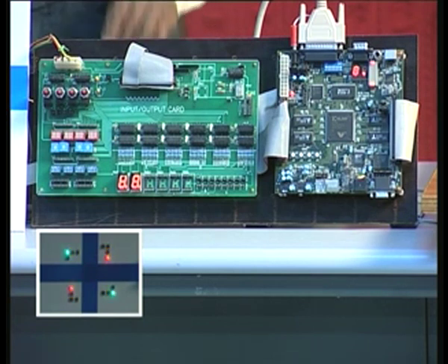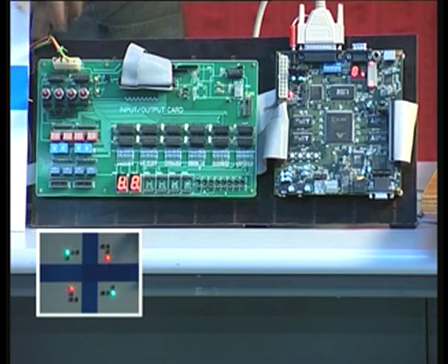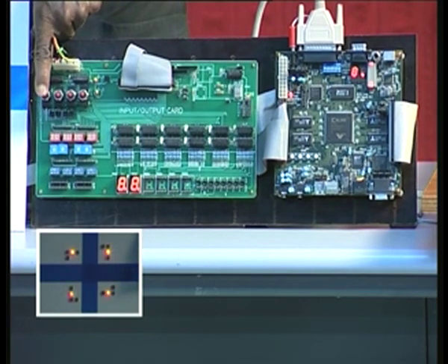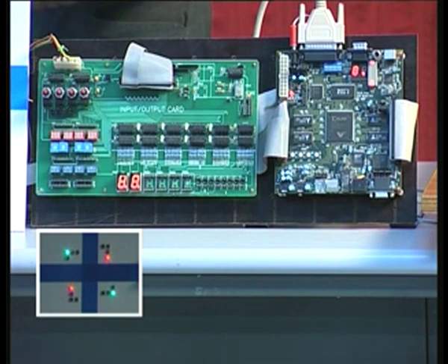While running through the normal sequence of the traffic lights, you also have the provision for pressing a blink control, and PB1 through PB4 that you see, one of them is used, namely PB1. If I press this one, you just watch what happens to the display, and you can see that it is blinking. All the yellow lights are blinking as long as this is switched on. This is equivalent to blinking of the lights during the night for cautious driving, and when you release, it reverts back to the very first sequence that you see there.